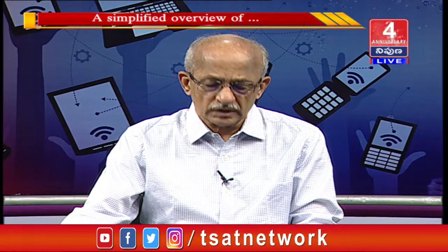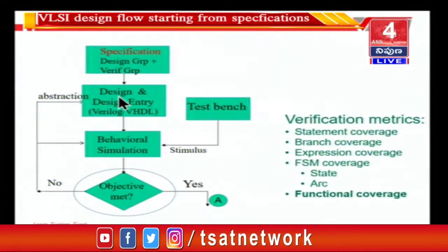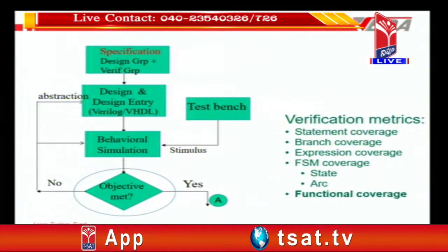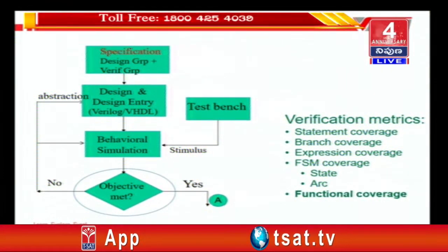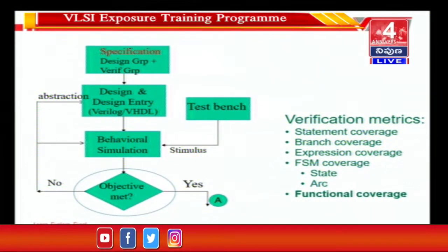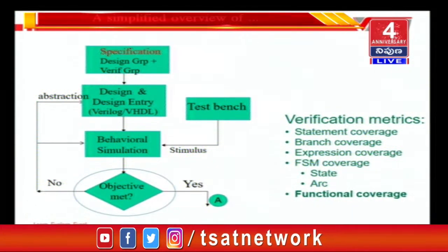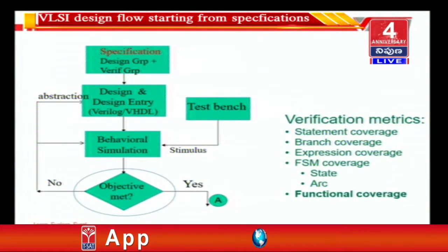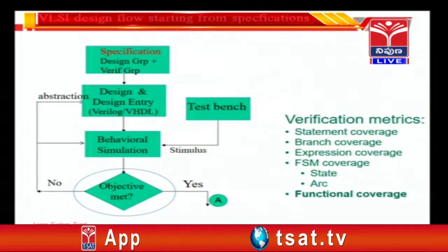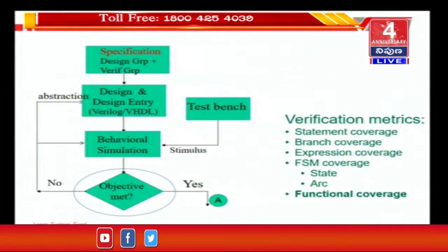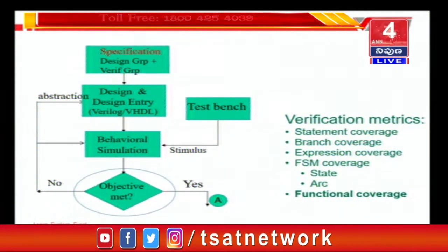Okay. Now that software form can either be in the form of Verilog HDL, the Verilog language, or in the earlier years it was schematic capture. Schematic capture means drawing logic gates and interconnecting them on the system. In the previous years, we had software like PCAD, ORCAD, Tanner, LEdit and so on, which were there for schematic capture. So the design was captured at a schematic level, that means at the logic gate level, and then stored into the system through the interconnections.